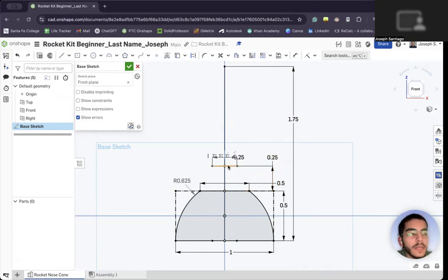how to move things. Now, what we're going to do is take the arc tool again. We're going to go from this point to this point, and we're going to pull out. You can see it closes the shape, but what we're going to do is dimension this. So we're going to 0.313. And then on this side, well, actually, the mirror tool. So we're going to hit mirror, and we're going to click this. There you go. So now you have two sides.